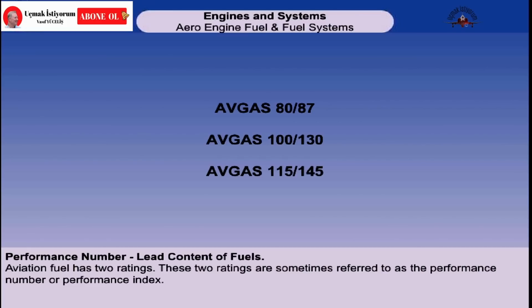It follows that if an engine is designed to use a certain grade of fuel, then a lower grade should never be used, as this would cause detonation. If at any time the correct octane rating is not available, then a higher octane rating must be used.